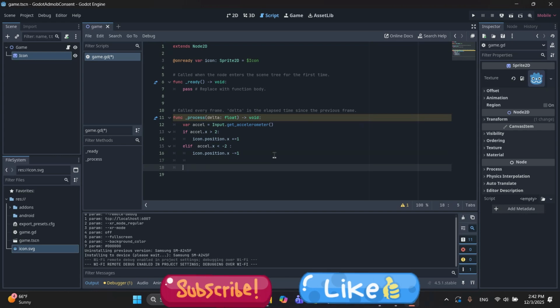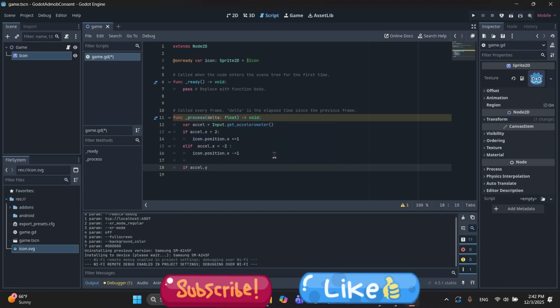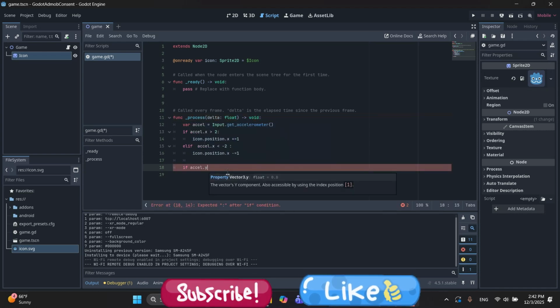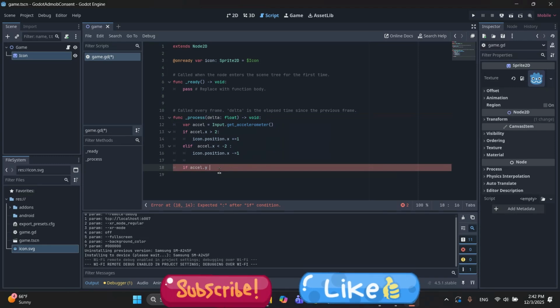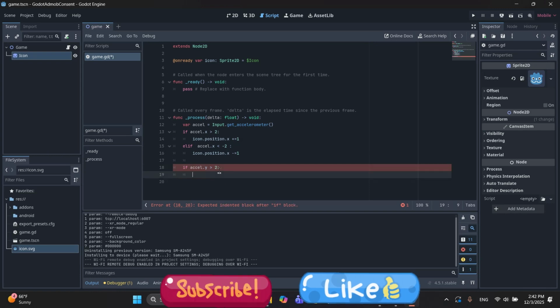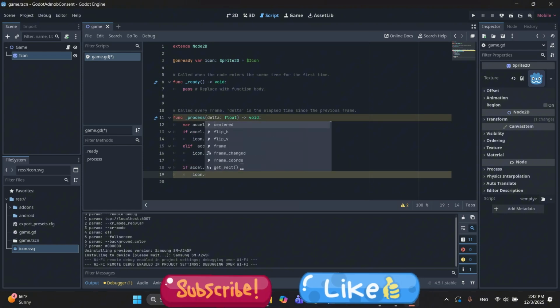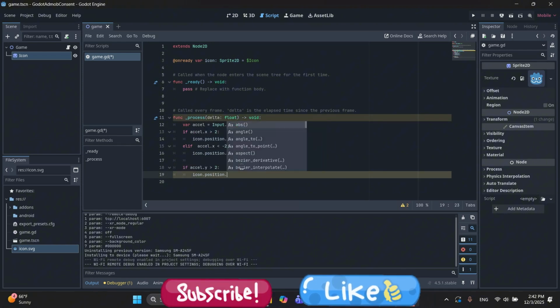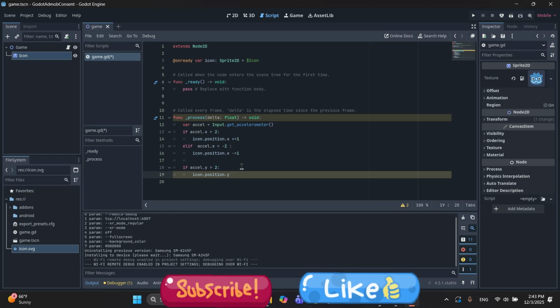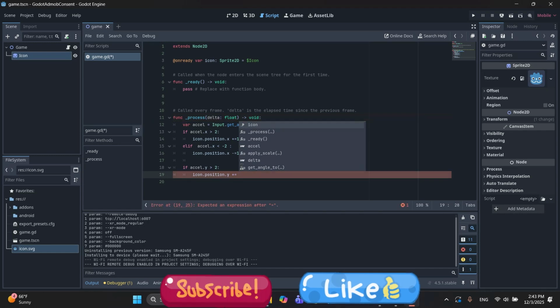And for going up and down, I'll do the same. If ACCEL.y, I will use the second component of the output from the accelerometer, and if it's greater than 2, then I'll move the icon.position.y up.